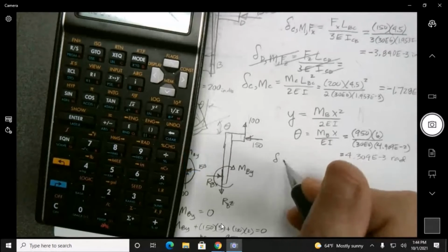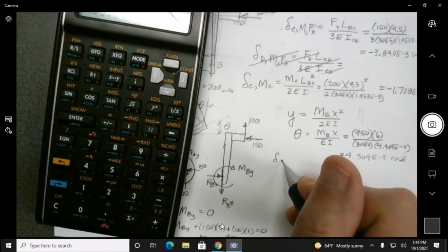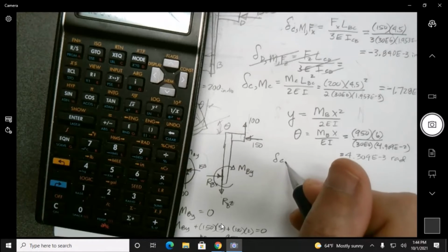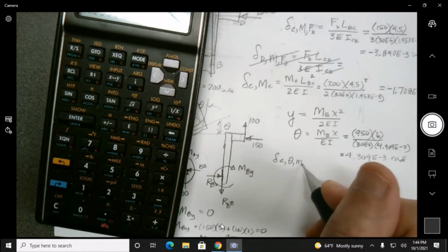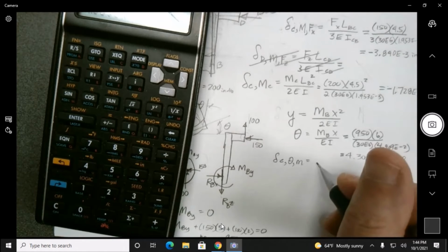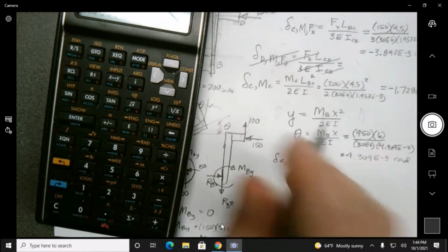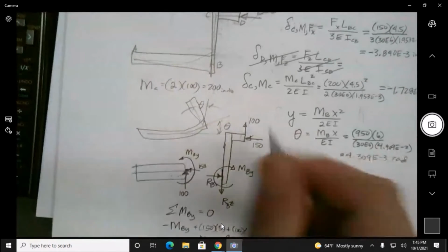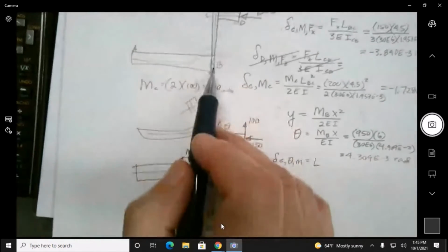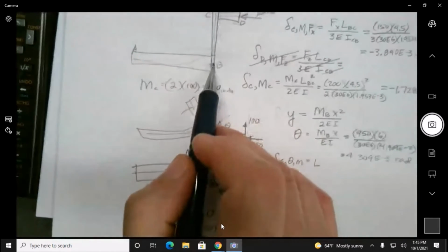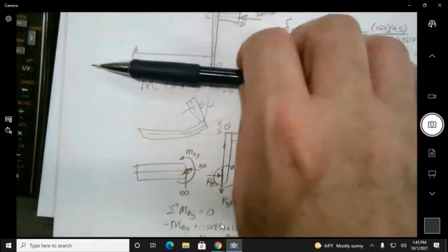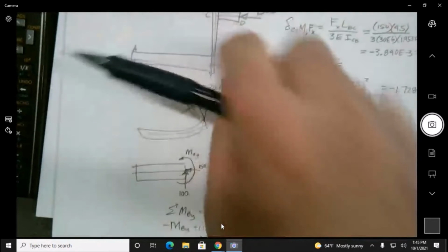So the deflection, and this is really C that's deflecting, is going to be due to that theta, which is due to the moment, right? I'm really screwing up my thing. It's just going to be the length of BC, this length, and we use the full length, not the 4.5, because it's from the center of what we're looking at.